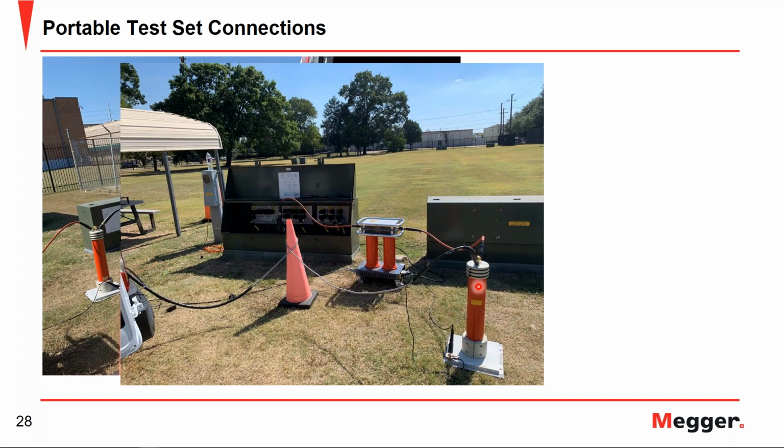You want to make sure to place this before our coupling unit. So from our high voltage detection unit, our high voltage cable goes out to our support capacitor, to our coupler, and then to our cable under test. Again, a pretty straightforward connection. And that communication box that I was talking about, you can see this cable here comes to the coupler itself as well. Actually, on this side, you can see it wrapping around.